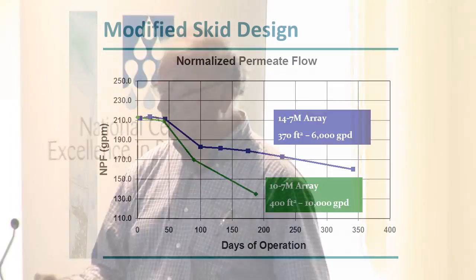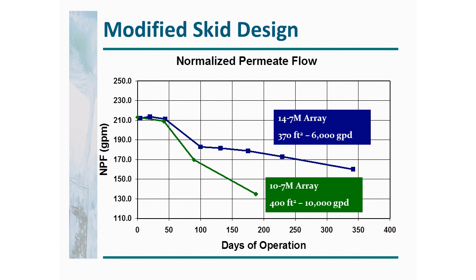And here you see that the permeate flow rate would go down in both cases because we achieved a higher cross-flow velocity, but we had upped our flux. So the concentration polarization was the same for both cases. And of course the energy use went up.